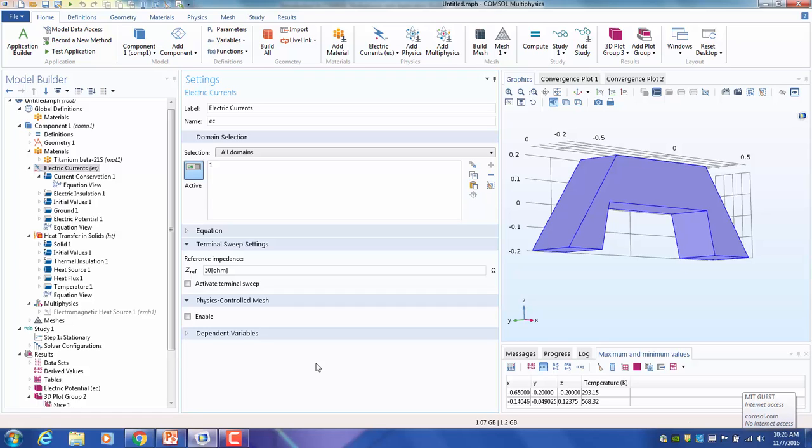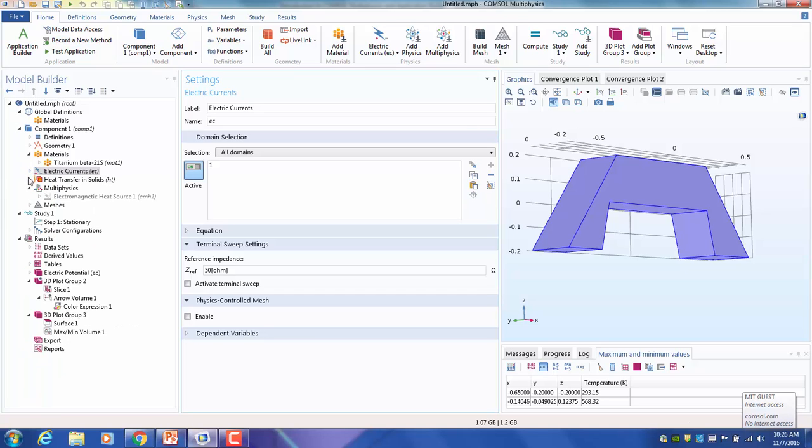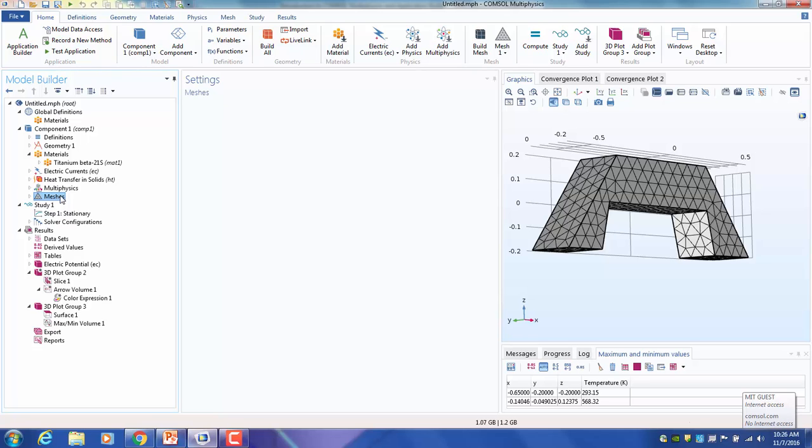Another important point, since you mentioned it, is for numerical solutions: so far, can we trust the results? Can we trust that 768, 568? Maybe, but I wouldn't trust it to the digits, because so far we're using a relatively coarse mesh. In numerical studies, you can start with a coarse mesh so that it solves faster.